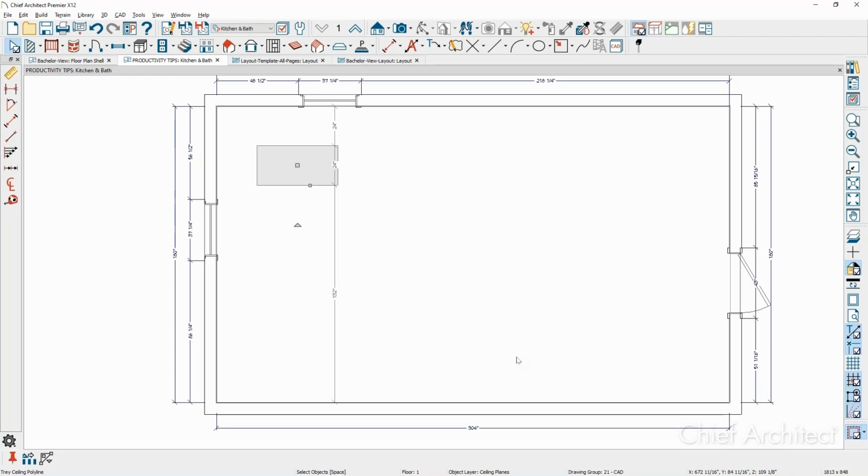Okay. Rick, are you using a PC or a Mac? PC. Okay. It works slightly different on a PC. If you look up multiple copy and you're on a Mac, it works slightly different using your keys. Now that that interval is selected and I move my mouse over this tray ceiling object, you see my cursor change. Here's what I do.